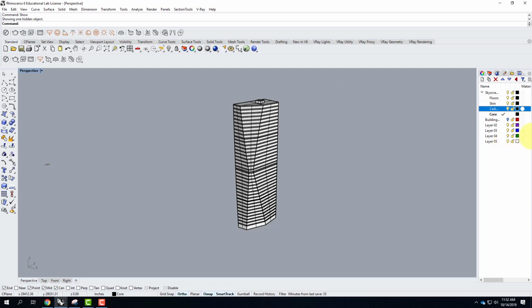And so you guys remember back to this part of it. I'm going to create a layer for environment. I'll create a sublayer under environment for light. And I'll create another sublayer under environment for infinite plane. There we go. And so on the infinite plane layer, I'll go ahead and click on the V-Ray infinite plane tool.